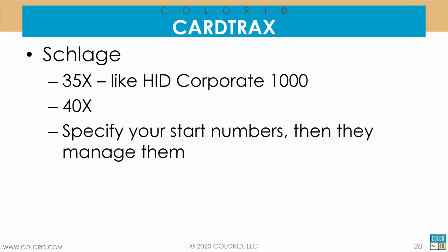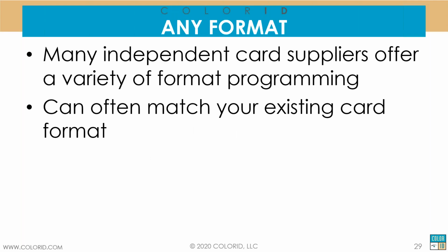Now, once you go to the encrypted cards, these same formats are the numbers that the access control systems look for, and they can be applied to either type of card. So whether it's a PROX card, iClass, MIFARE, DESFire EV1 or 2, SEOS, all of them are normally programmed with one of these formats. Also, other manufacturers that do card programming are now programming a lot of these formats. So if you can't get it from one manufacturer, you might be able to get it from another.